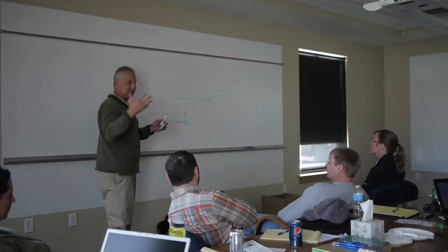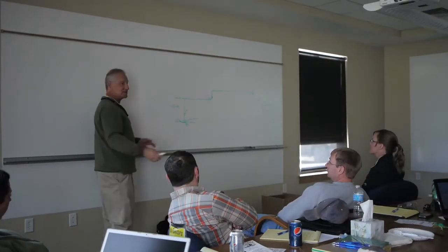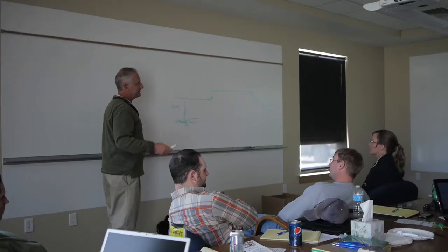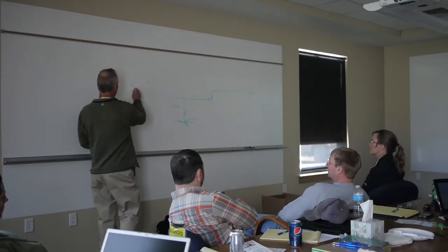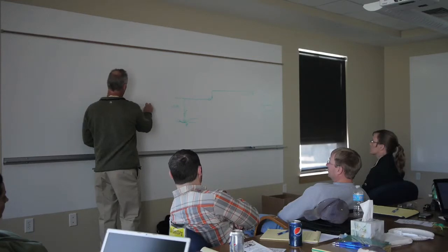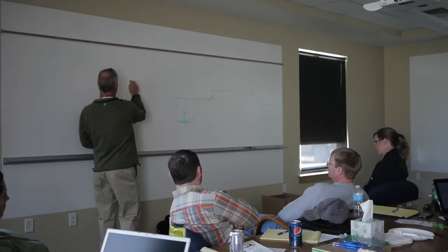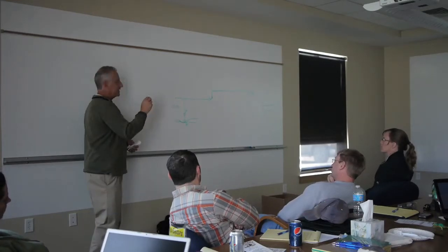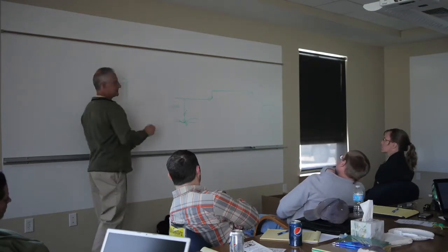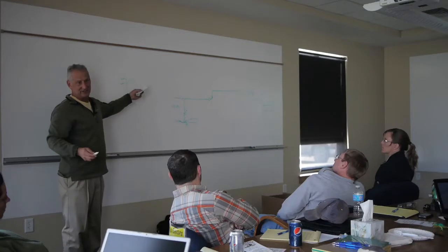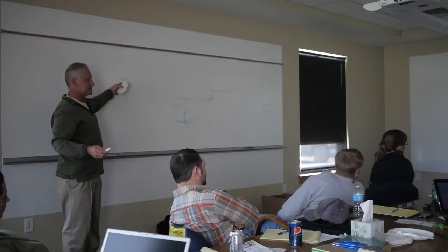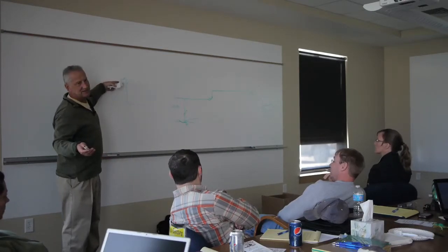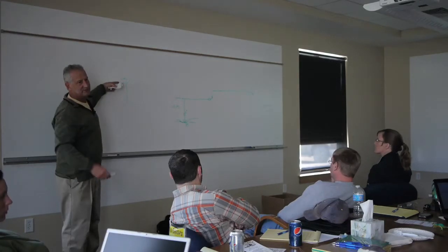Here. If you had a 600-foot well, and you just need 40 psi, 600 feet is, let's just call it 300 PSI. So here's 300 and here's 340. Okay, PSI. You see the system trend is there. You can only vary the speed that much. And so in that case, the cost of the variable speed drive is about 10% of the total range of the pump.